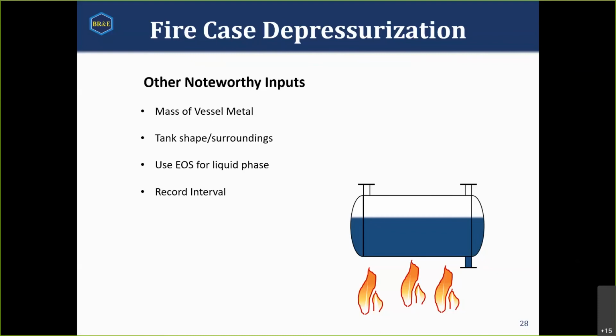It will not output each of those time steps. If there is no appreciable change between two time steps as far as mass flow goes, it'll go longer before it records anything. However, it will take a calculation step of no longer than that value.